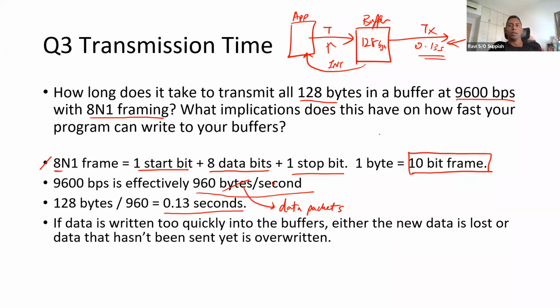In some cases, maybe the UART took a bit longer to update one of the registers, and so on. So it is not to say that this will go on perfectly at the same rate all the time, but this will be the general rate. So instead of using a timing approach in a solution, it's better to use a notification approach. That means once I finish, I'm notified, maybe by interrupt or by some flag, a global variable flag or something, and then I do the next.